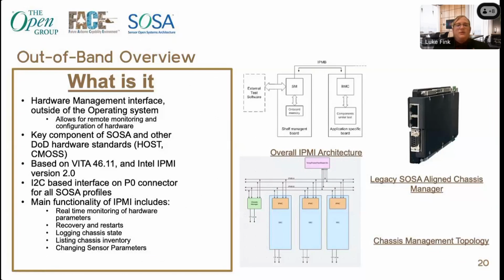It is a hardware management interface that exists outside of the operating system. It allows primarily for remote monitoring and configuration of hardware. So some of the functionality of that is real-time monitoring of hardware parameters, like potentially voltage or temperature sensors, as well as changing parameters on those sensors, such as the thresholds that trigger an alert or a hysteresis value. It can also log the state or errors that occur in that chassis, as well as handle restarting and power